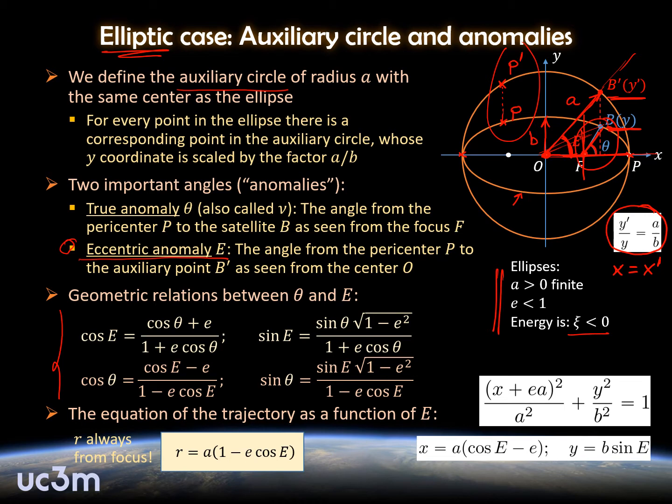Using the eccentric anomaly that we have just defined, it is possible to recast the expression of the trajectory, and it actually looks a little bit simpler. It looks like this. Okay, so you see that as we vary the value of E, we have a constant part. Basically the first part of this equation corresponds to a circle of a constant radius a, and the second part is a variable term, a sinusoidal, cosinusoidal term, that goes with the eccentric anomaly. And this allows us to represent an ellipse not from the focus but from the center using this eccentric anomaly.